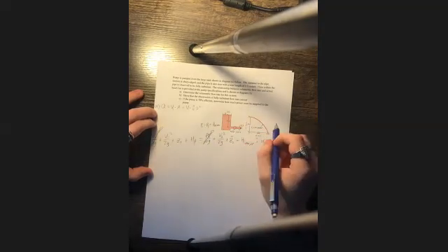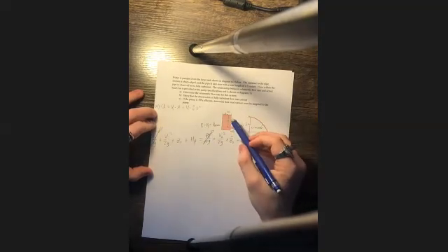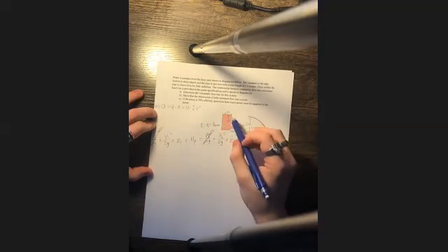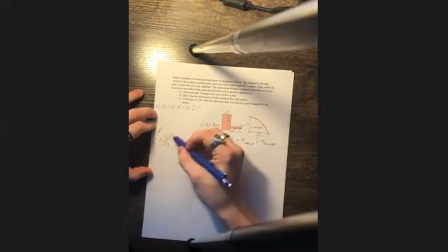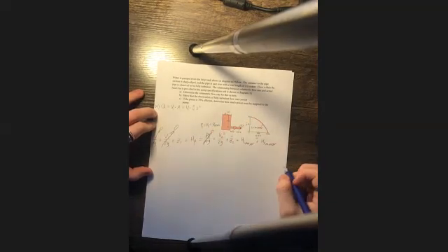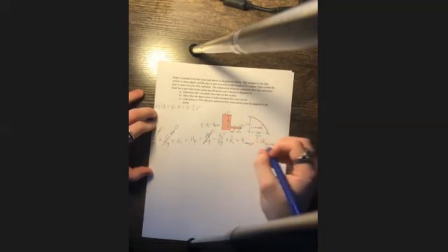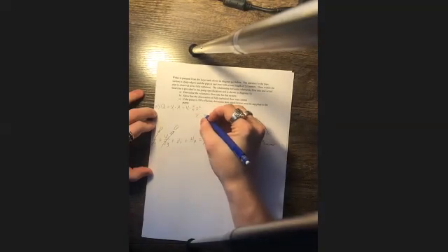We can cancel those out. Okay, like I said before, at the top of a large container that's draining, the velocity is going to be close to 0. So we can cancel that out. Z1 minus Z2 equals 6 meters. We're given that right here. Head of the pump added is going to be 20 minus 2,000 Q squared.